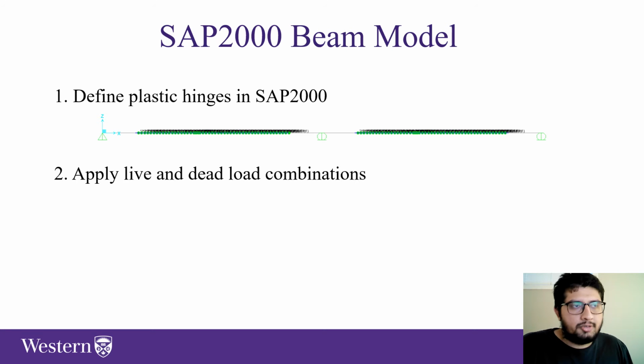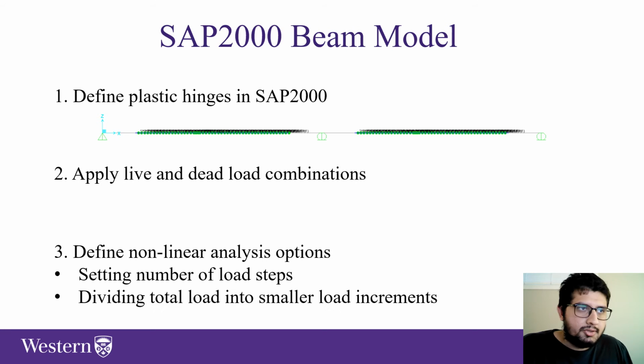In SAP, we also have to define the live and dead load combinations, and we have to define the nonlinear analysis options, which include how many load steps we want, and we have to divide the total applied live and dead load combinations into smaller load increments.